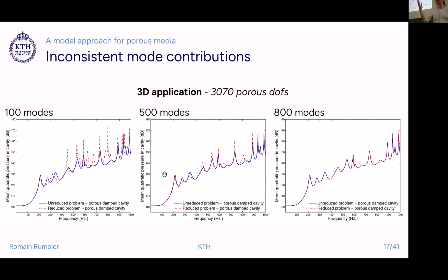Reduce the number of modes that you would need to calculate. I will not answer that. I think, Ravi, this is something that when you have a very rigid structure and then a very soft structure associated with this, you have these kind of problems where you have a lot of modes that are coming to pollute the basis. I'm not going to look into that. It's a complex question, but it's an interesting one to look into.